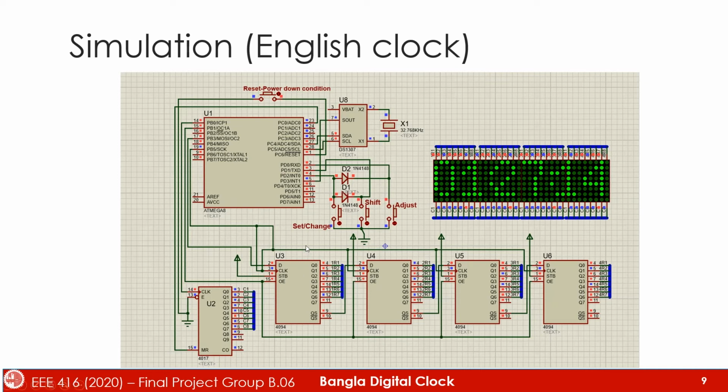The 4017 IC is used to activate the columns and four 4094 ICs are used. Each 4094 is used to assign high or low values to the activated columns. Suppose column 1 is activated by 4017, and now 1R1 to 1R7 will decide the 8-bit logic of the corresponding column.